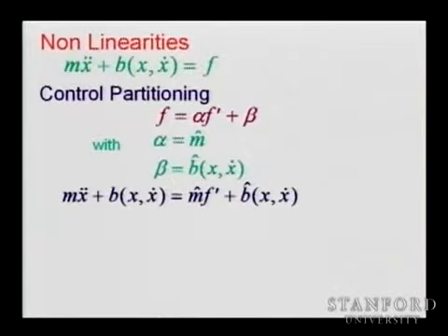So here's the result. If B and B hat were identical, if B hat was compensating perfectly for B, and if the estimate of the mass matrix, later, this mass was identical to M, then your system will behave this way. So what you designed for F prime will be part of the closed loop of the whole system. We're talking about 1 degree of freedom, but later we will see 20 degrees of freedom, it will be the same. Okay?